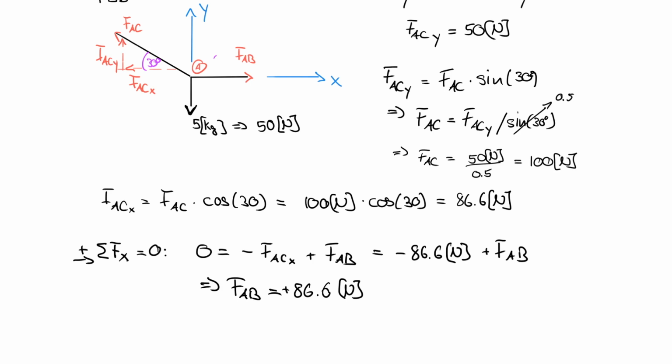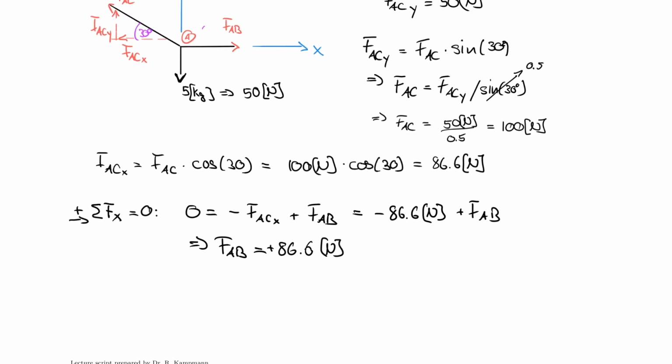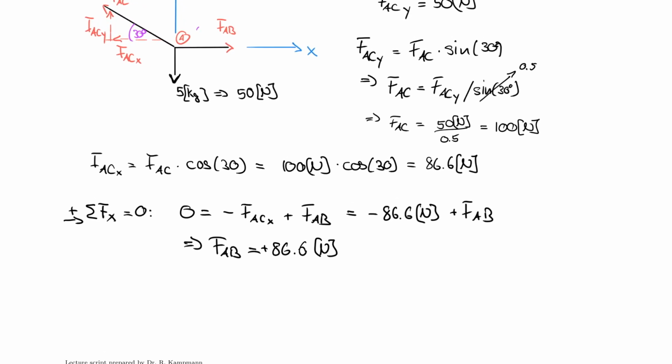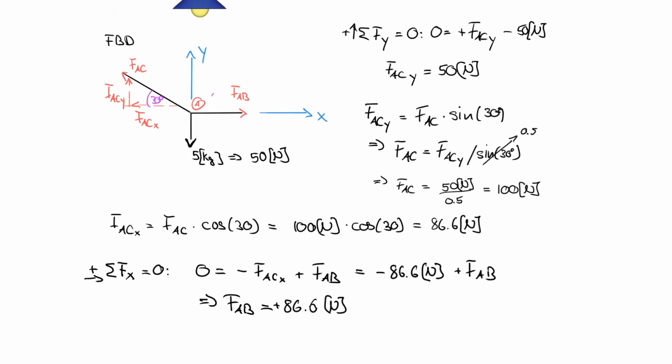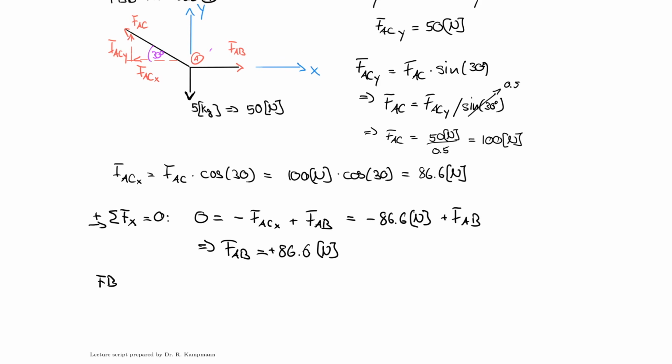All right, but we are asked to find the stretch in the spring, and for the stretch in the spring, we can actually draw a second free body diagram. So to be complete here, for node A, I'm now going to draw a free body diagram for the spring. So free body diagram for spring. And that is as simple a free body diagram as it ever will get. So I release the spring and I just have a force here and a force here.